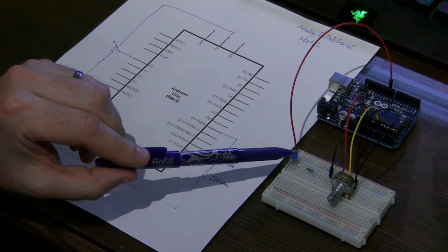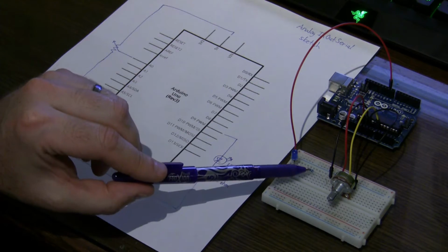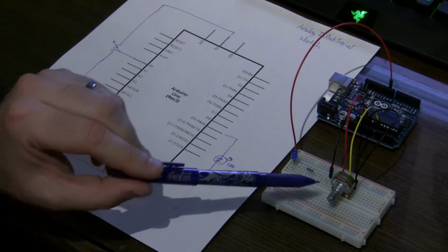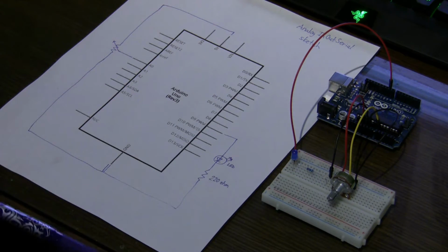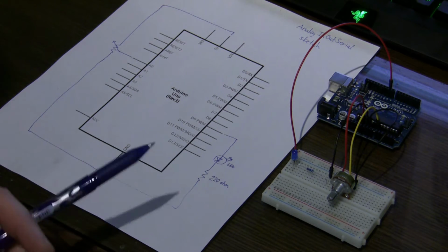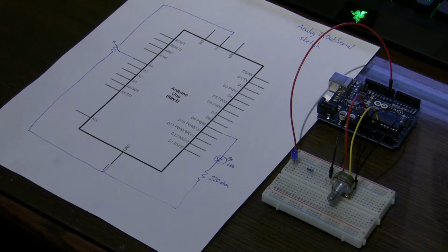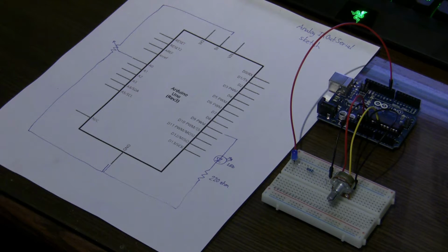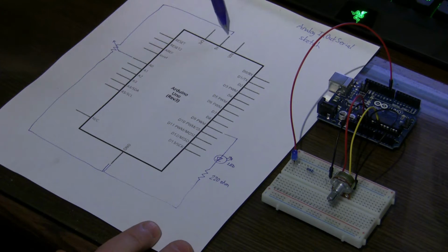You're going to need an LED, a resistor that's 120 ohms or greater. I'm using 220. And you're going to need your 10K variable resistor. So this one's kind of a mashup of some of the earlier sketches from this chapter. This is putting together the fade sketch and the sketch where we're using the variable resistor and taking a reading off the A0 pin. So in this one we've got 2 circuits really.